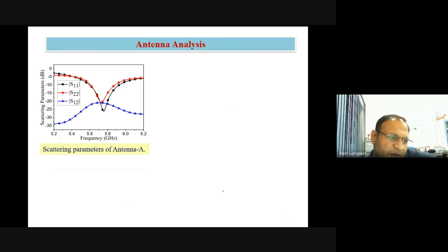So now first we have to check your first DR element, which is going to be excited by two different ports. The first thing is that we have to see whether they share similar impedance bandwidth or not. So here you can see that both share similar impedance bandwidth. That means the 5.5 gigahertz band is fully captured here.